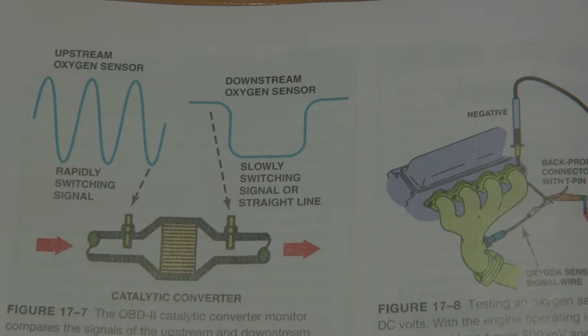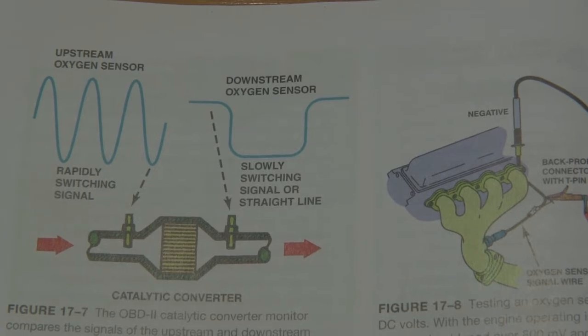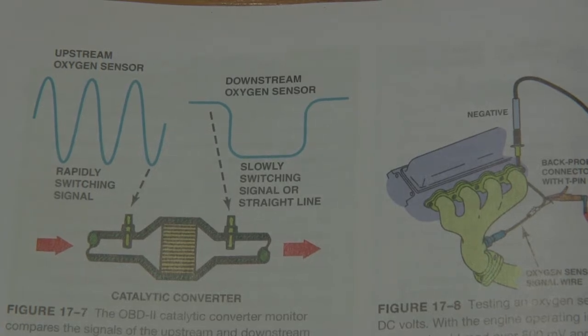Downstream oxygen sensors can, but typically don't, affect air-fuel ratio. They do not affect air-fuel trims. There are cases out there, there are vehicles. As a matter of fact, we just worked on one in the lab. It was a Nissan Xterra 2000, 2001, where technically it had the ability, if you read through the circuit descriptions, in the event of an upstream oxygen sensor fault, it would reference the downstream oxygen sensor.